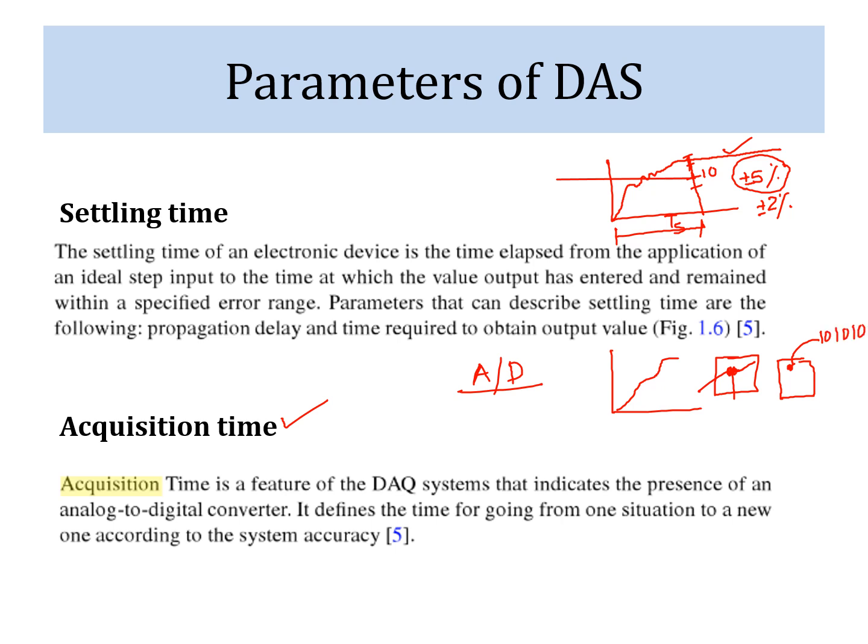So, the time within which any analog quantity is being converted into digital one for the next transmission is known as acquisition time. The complete acquisition time definitely depends upon A to D acquisition time as well as other time delays within the signal, but minimum acquisition time will be equal to the conversion time of A to D for analog to digital conversion.